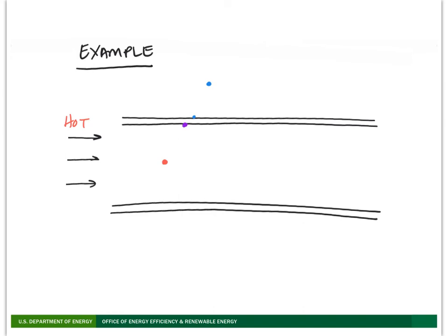If we turn this into heat transfer diagrams, which can be helpful for us to visualize this, we have heat transfer through the air in the center of the duct, and that would be convection, and then we have conduction through the solid wall of the duct, and then we have convection again between that wall of the duct and the air around it, because that's the colder air outside in the attic or in the crawl space.